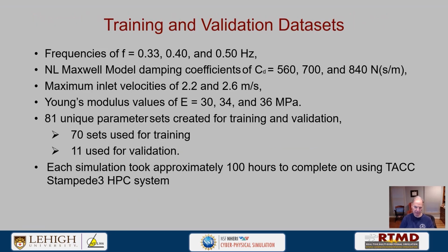So look at different training and validation data sets, and different frequencies of the incoming fluid. Again, in the modeling there, we first used OpenSees with the fluid dynamics calculations coupled to that, where the nonlinear Maxwell models were used to develop the training data. The inlet velocities are shown there, and the Young's modulus of the members is varied.